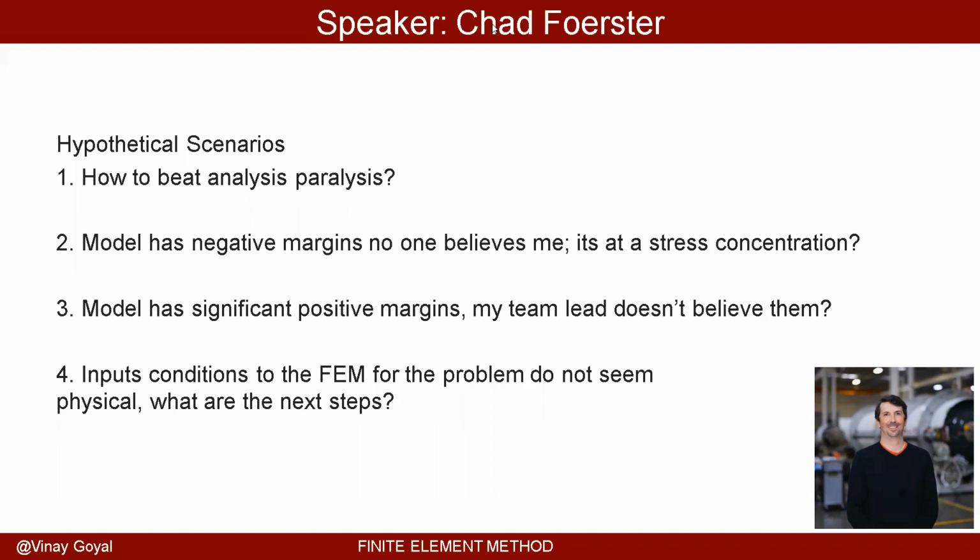Stuff like that, right? Yeah, and the other approach, Chad, is potentially to do a subcomponent level test of the area of concern. That's a very cheap test, not expensive. Absolutely, right. That's like that breakout model, and it's the test analog of that breakout model. That could be an interface test. We did some work at Aerospace on composite core ramps and published that data in AIAA, and that's an interface test, right? So that's a breakout model with a core component that helps you make good decisions on a large structure.